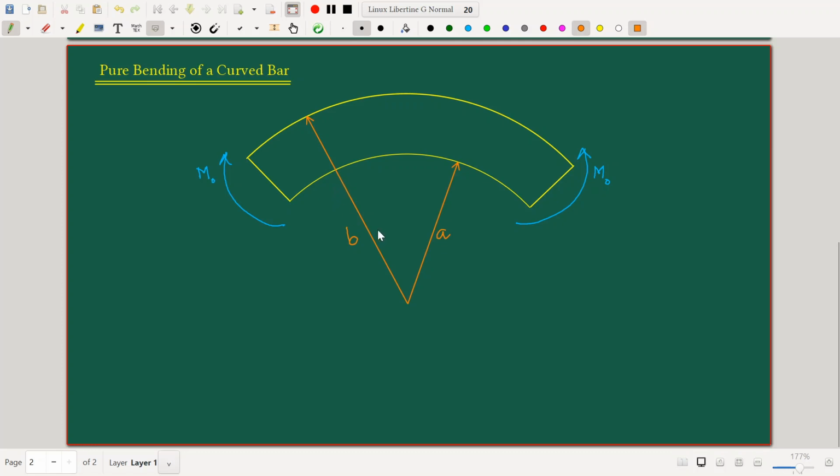So just as we had done in the case of our previous problem on the pressure vessel, we can note immediately that at r equal to a and at r equal to b, we can write down the values of sigma rr. And they are very much zero for this problem, unlike the pressure vessel where we did have an internal pressure acting at radius a and an external pressure acting at radius b. Here we do not have any such pressure, so the values of sigma rr both at r equal to a and at r equal to b are going to be 0. So we write that down first of all: sigma rr equal to 0 at r equal to a, sigma rr equal to 0 at r equal to b.